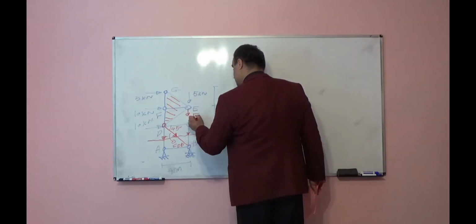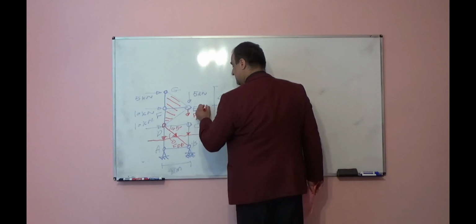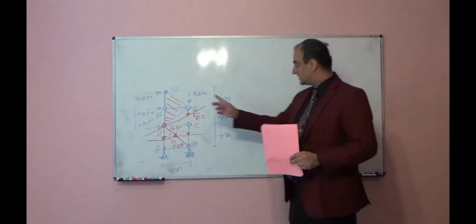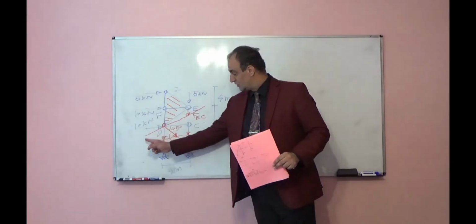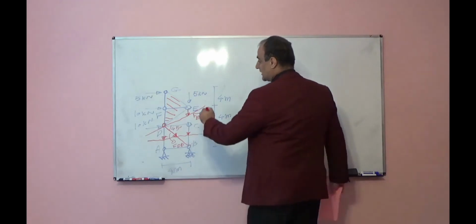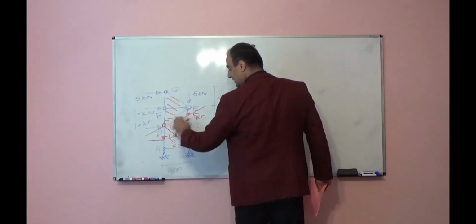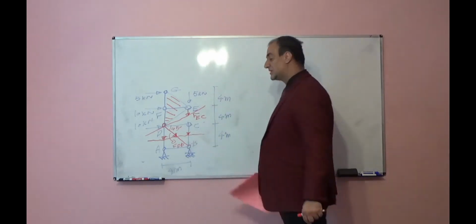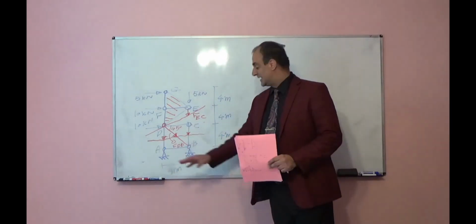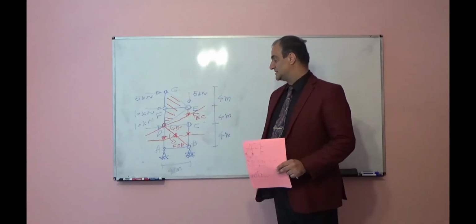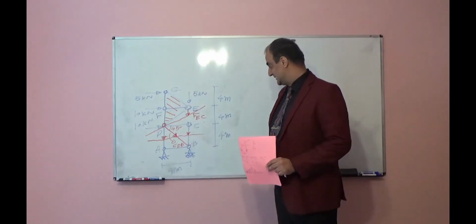So FEC, I will cut this member through joint or hinge D, and I will keep the top side. You can keep the bottom side, but in that case you will need to first find reactions, because reactions are unknown. Always, you see, I'm keeping the top side. This makes calculation faster and easier.